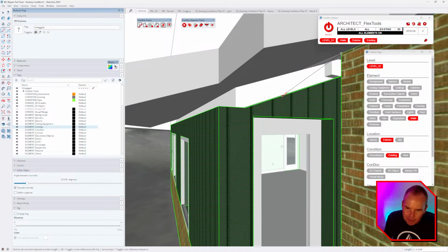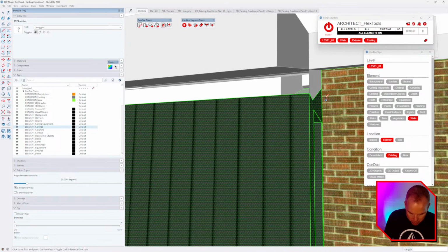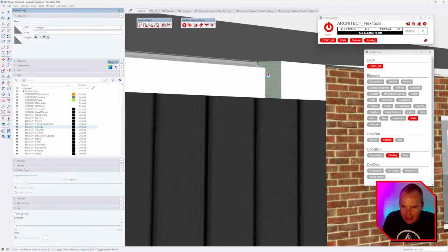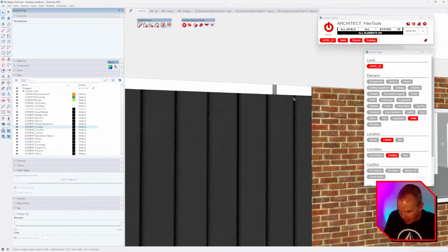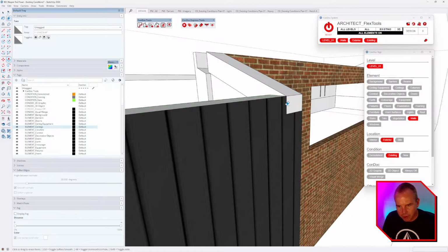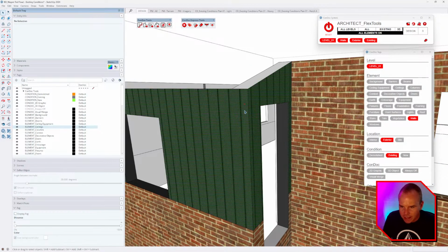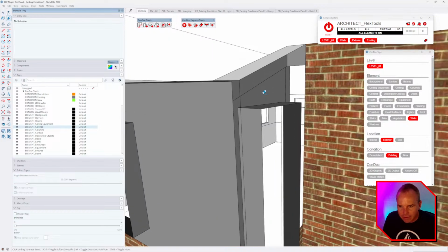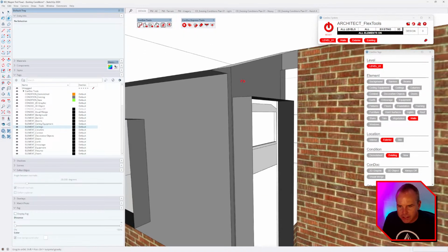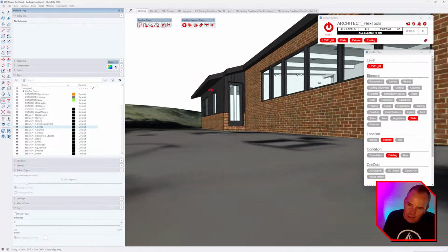There's a million different inferences here. You can tap down to lock that inference, hover on this edge to project to that intersection. I can push pull this guy back to here, and then hide rest of model. This, I believe, we just need to push pull up like that, and then clean that stuff up. Same deal, hide any of these extra edges that we don't want to see, because they will find their way into your drawings.